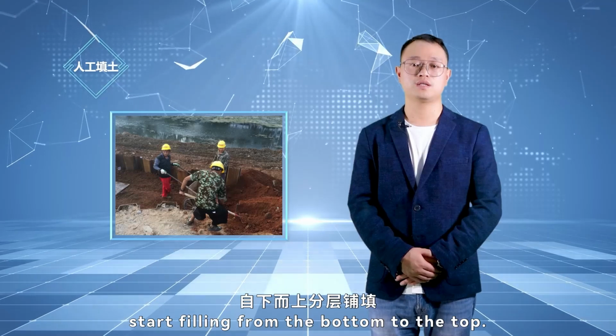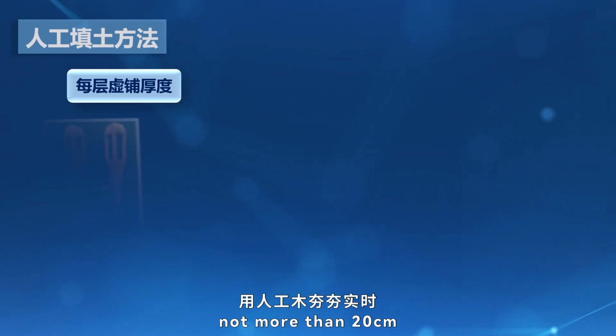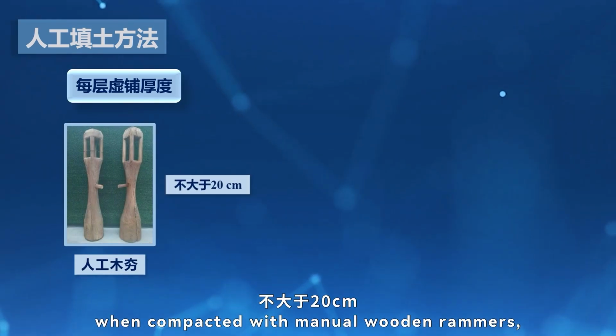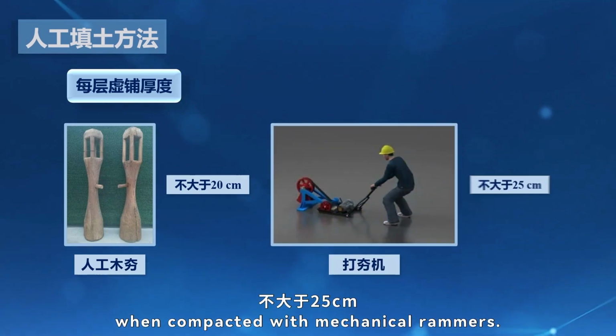Start filling from the bottom to the top. The thickness of loose laying of each layer should be not more than 20 centimeters when compacted with manual wooden rammers, and not more than 25 centimeters when compacted with mechanical rammers.